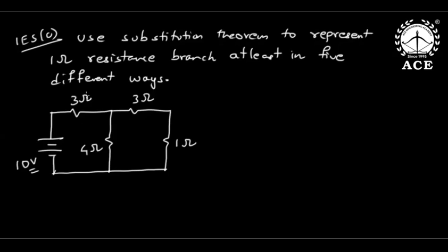So now everybody should see this. First of all, let us observe what is happening. Total resistance seen by the source is 4 parallel to 2, plus 3, which is 5 ohms. When 10 is seeing 5, it is 2 amperes. 2 amperes will divide the current, then this is automatically 1 ampere. When 1 ampere is going through 1 ohm, it is 1 volt.